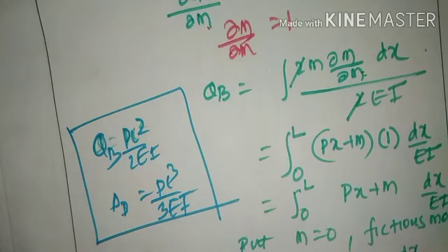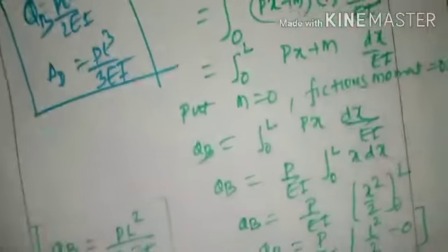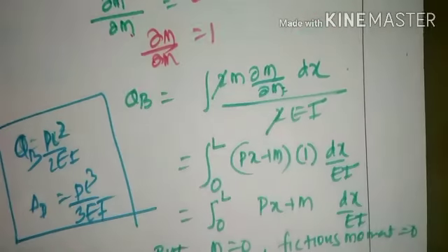When we partially differentiate, we need to ensure that a concentrated load or a concentrated moment is present at the location where deflection and slope need to be calculated. If not, we need to introduce a dummy force and a dummy moment and later equate it to 0 during the process of integration. Further, we shall solve some more problems related to Castigliano's theorem.